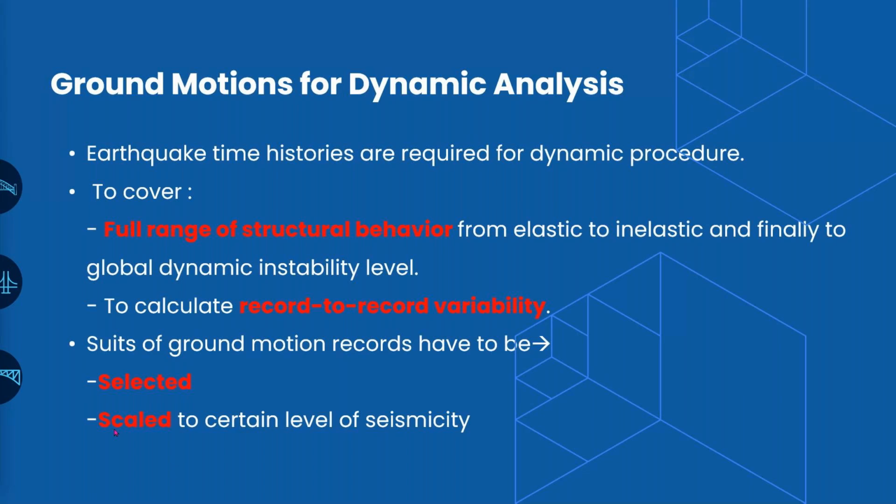Generally, the scale factor is considered to be within the range of 2 to 4. So we should not scale the ground motions with scale factors which are generally more than 4, because it will not reflect the correct behavior or the correct characteristics of that particular seismic event. So generally a scale factor range of 2 to 4 is valid, and this scaling is done in the time